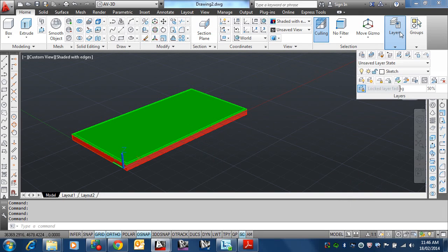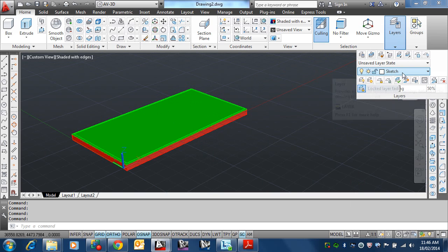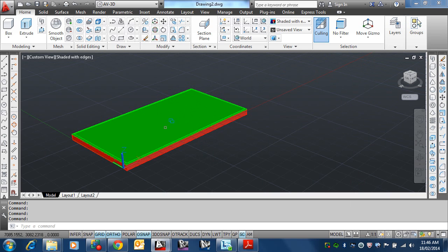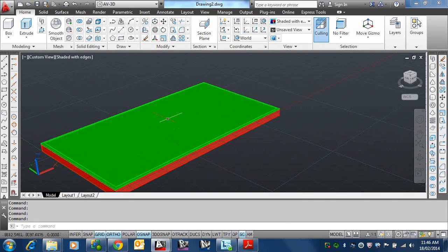Okay, so we're going to put the rebate somewhere in here. So make sure on my sketch layer, which I am, I'm currently in this UCS format here. So let me just draw a rectangle somewhere on here. Let's start off with this rectangle command. I might take off the O snap, so I don't want to snap into anything. And I'm just going to draw something on here of the